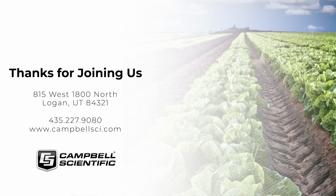So the other thing that can be a rule of thumb is how far apart the rods are spaced and whether it's a 2 or a 3 rod design, depending on the sensor, but that kind of gives you an idea of what the bounds are for how far the signal reaches and so how much volume is being measured. Yeah, that's a good point. The rule of thumb is if you take the distance between the outer rods, that's about how far from each rod you can go and still be within the sensitive volume.